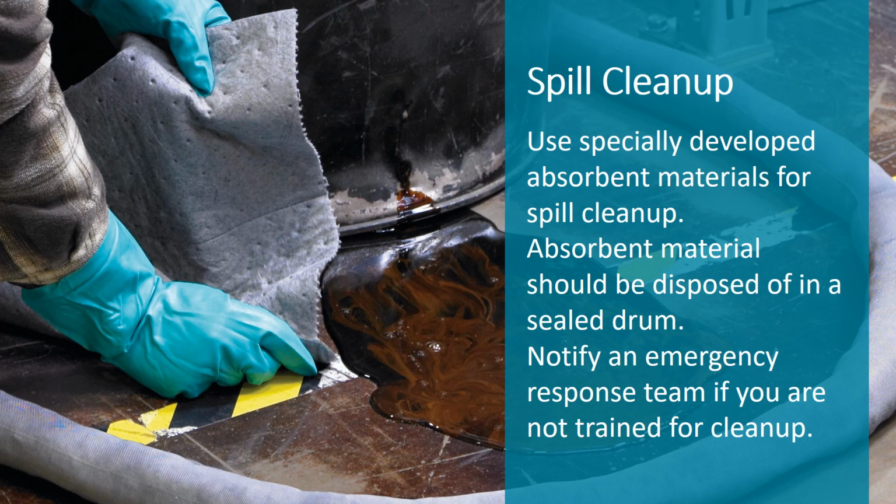If a spill or release requires an emergency response, do not respond if you have not received specialized HAZWOPER training. Instead, leave the area and from a safe place, call Crystal Clean, and then notify your supervisor. Crystal Clean's number is listed in your safe work procedures for all spills.